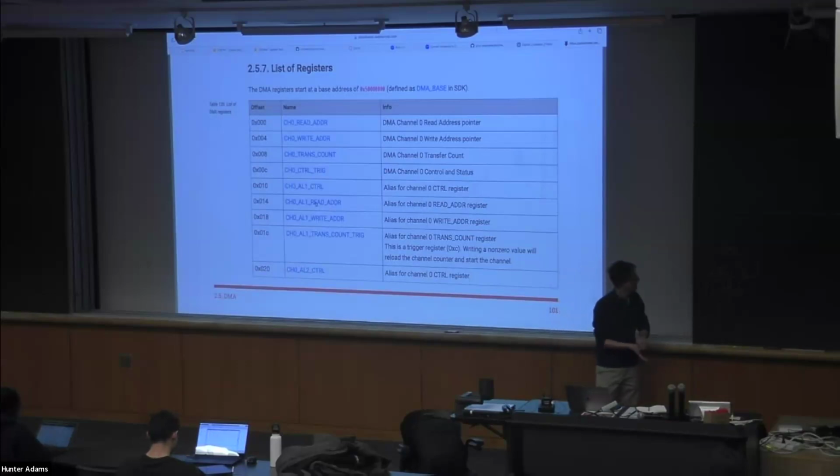Yes, and more specifically, the DMA channel in this lab is being used to move data from memory to a particular register associated with the SPI peripheral. And then the SPI peripheral is configured such that anything that lands in that register gets whisked away across the channel.